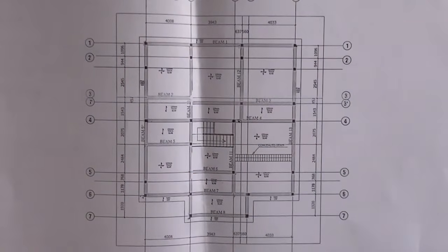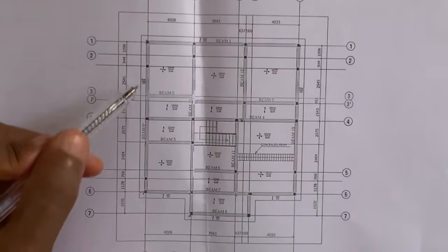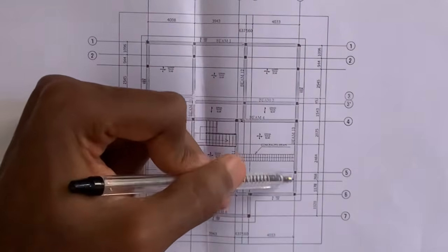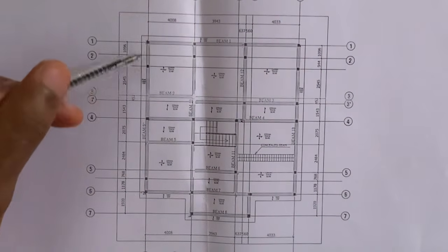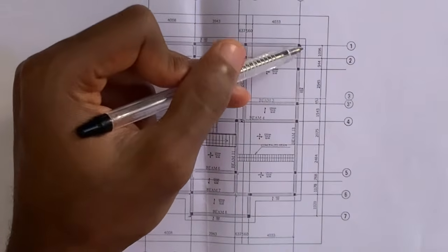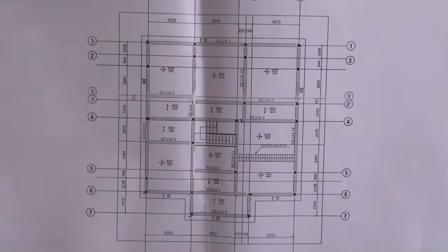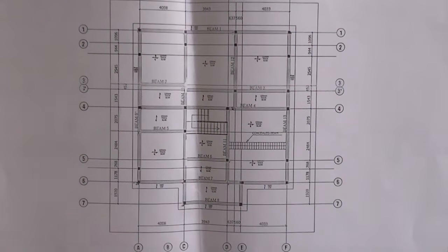The reason why this section does not include beam 13 is because what we have here is parallel and equal to what we have here. So it means that the details for beam 9 are what we're going to be using for the details for beam 13. These are the things you have to put in mind. You have to be smart when reading your drawings, because sometimes there is no need to replicate drawings 2 times, because what you'll be seeing in one might in some cases be the same thing that you are going to be seeing in the other.